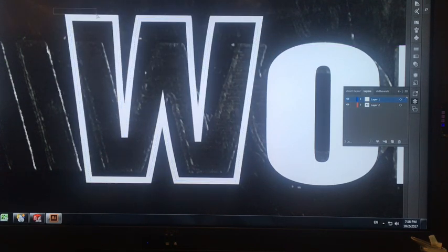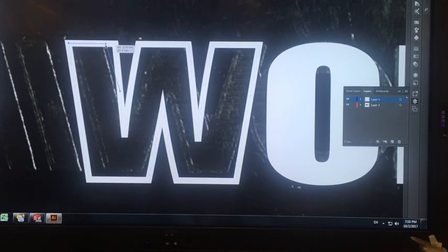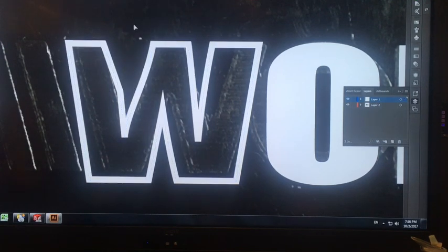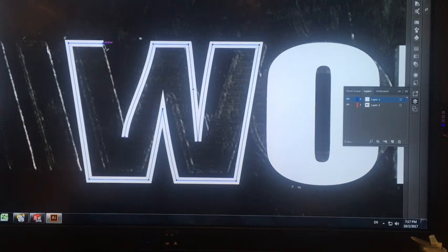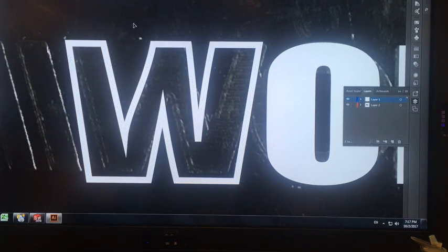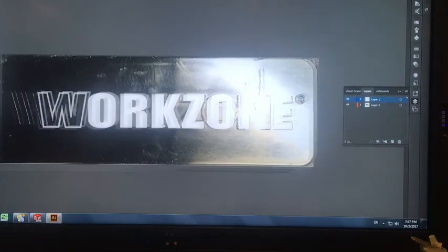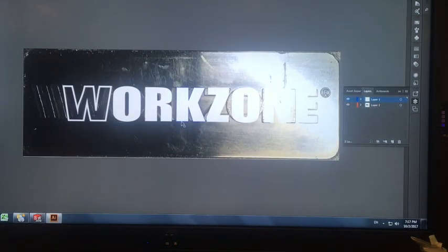All right, so if I want to reposition these letters to move them in or out, I can do it. Where there's lines like here, for instance, if I want to remove that, I can just delete that point, press P, and use the pen tool to draw a line between those two. There are different ways that you can create your own artwork to then export and import. It might be easier doing it in Illustrator, or if it's easy enough text and logo, you might be able to just import that image into SolidWorks and then sketch over the top of it.